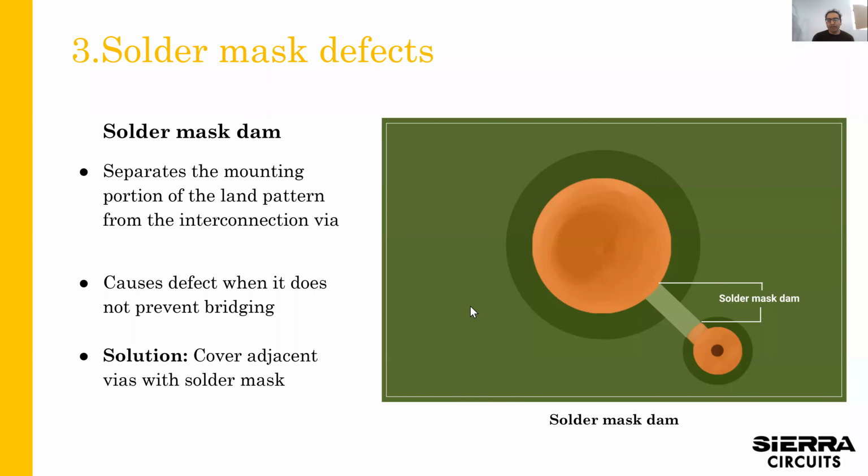If you have a very tight, high technology design, I would not leave it up to the fabricator. I would very clearly specify your solder mask layer and follow the right design rules at the same time. So you'd have to talk to your fabricator and understand what kind of solder mask feature sizes they can hold.